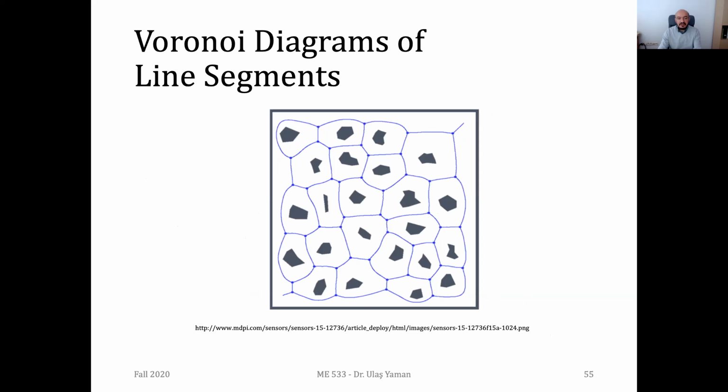Yes, we discussed the Voronoi diagram of line segments, but we can further have some different types of Voronoi diagrams. For instance, here you see some polygonal obstacles in the environment, and by following a similar algorithm, we can draw the Voronoi diagram of such a complicated field. As you see, these are not lines or points, and obviously, again, we should be checking the minimum distances.